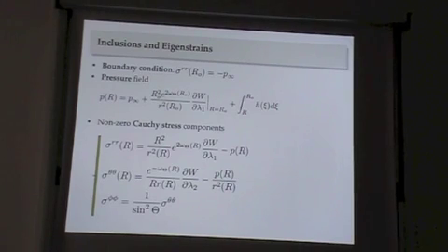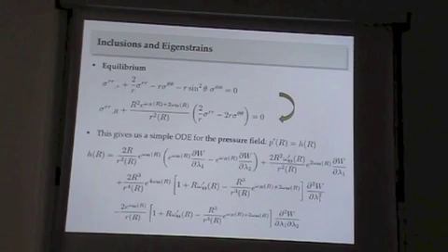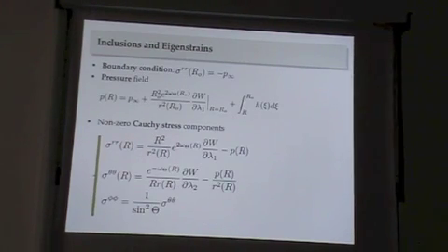Okay, so what are the boundary conditions? It could be traction free on the boundary, or pressure or tension. Again, this would still respect the spherical symmetry. So having calculated that P of R, and that H, I'm going to show you in a minute. And then the non-zero stress components would look like this after you have your pressure. Okay, so I'm actually going to show you. Okay, so this is H. So now, given any omega R and omega theta, I have the solution.